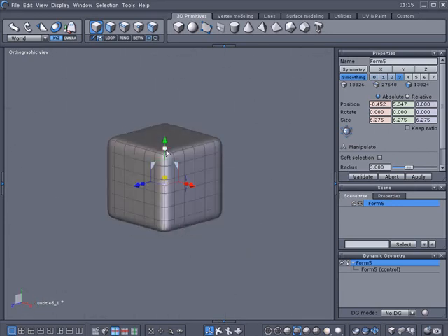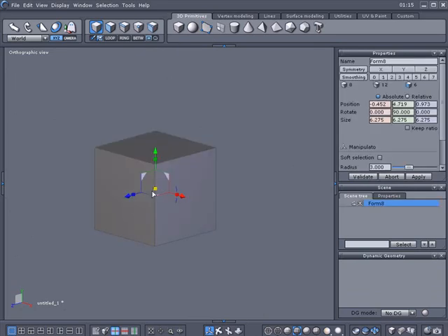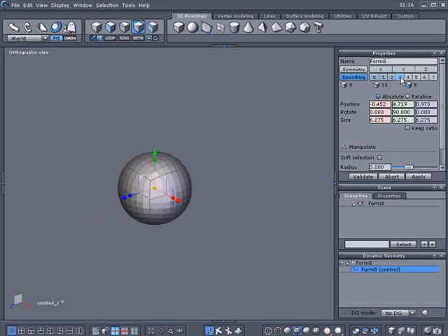And I'll give you a little scenario of what I think. Say I had this cube out here. Now the center of the cube, let's compare this to something. When you divide it, you're contracting it, and everything's trying to squeeze to the middle. It's trying to pull these points all to the middle. And it's also actually added more polygons to it. If I click this little icon here, as you can see, I got a lot of polygons there. I'll Control Z that.